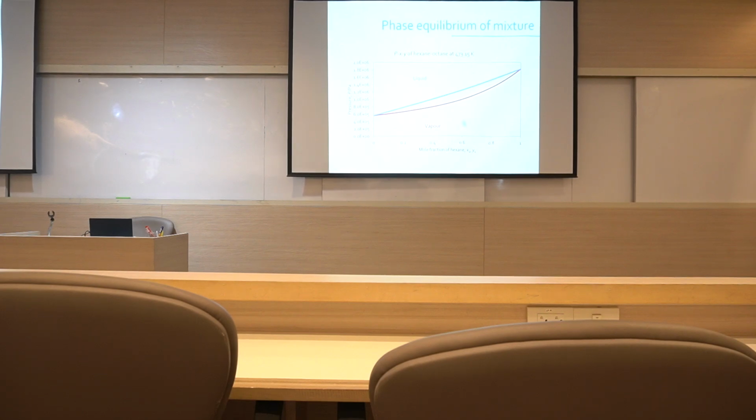And then in the middle, in this region between the liquid and vapor regions, that's where we have vapor and liquid coexisting in the same system. That is where we have vapor-liquid equilibrium. Normally when we use this diagram, we draw a tie line. The tie line is basically, in this diagram, the line at a constant pressure linking the mole fraction of hexane in the liquid phase to that in the vapor phase.